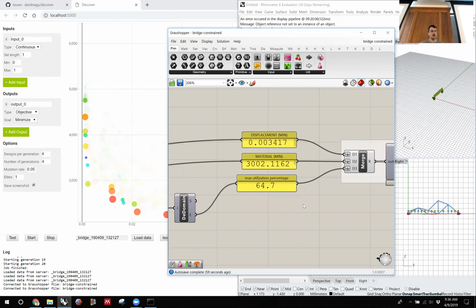And so when we start to think about that as a goal for optimization, we can think first, do we want to implement that as an objective or as a constraint? And so we could implement it as an objective and basically decrease the maximum stress in the structure. But usually when we think about structures, that doesn't really make much sense because stress is a natural product of a structure, right? We actually want a structure to take on stress. That's what a structure is supposed to do as it carries the load between the load point and the support. So we don't really want to minimize stress. That doesn't really make intuitive sense. But we do want to ensure that the stress isn't so big that it breaks our structure. That's why typically stress is considered a constraint.